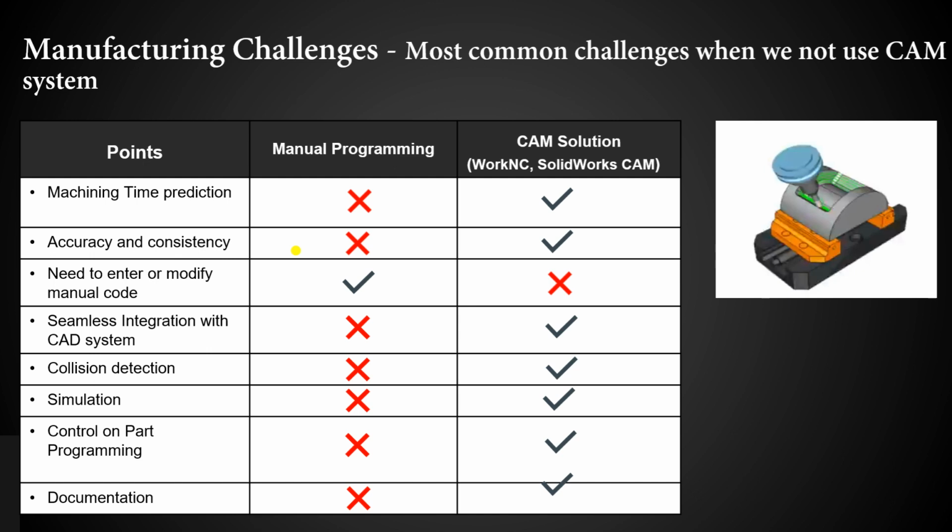environment also. Suppose you have a 5-degree draft, you can amend it to 7-degree or 8-degree. Your radius is 2 mm, you can modify it to 3 mm. You can also do it in your CAD system. You can analyze your body, where is the 2 mm radius, 3 mm radius, all things.